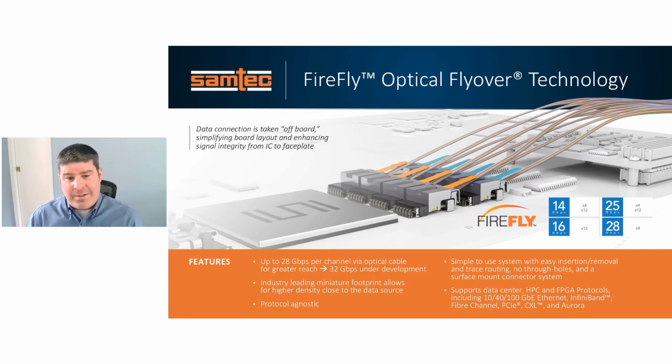One last technology we want to introduce. We're seeing a ton of interest within the ecosystem for AI for PCI Express and CXL over optics. Samtec is the leading provider of midboard optical transceivers within the industry. Our current Firefly optical flyover technology offers data rates up to 28 gigabit per channel with a roadmap to 32, which we should have available here in the next couple months. We also have a next generation platform which provides a roadmap to 56 and 112.